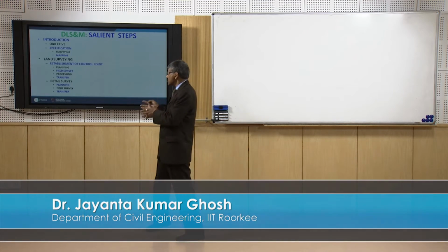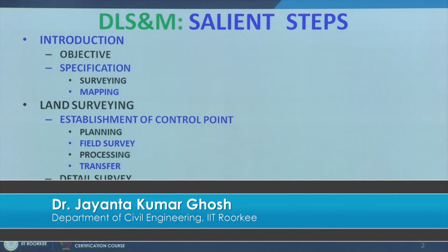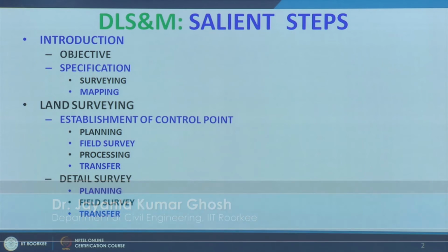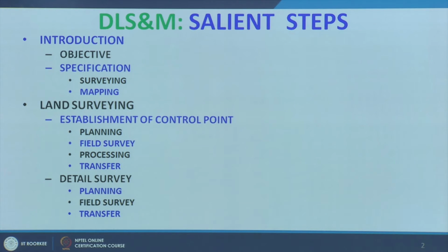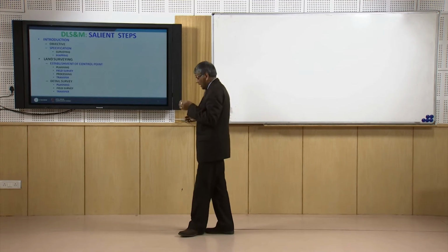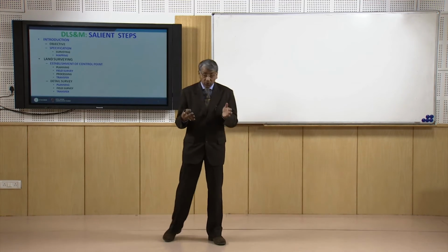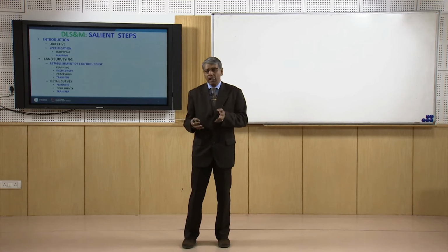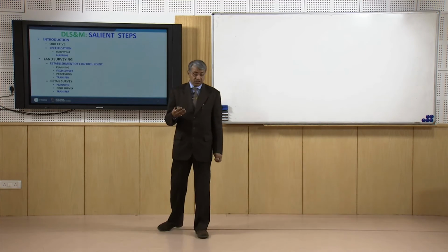So planning consists of first visiting around the area, called reconnaissance survey, and reconnaissance can be done in 2 steps. First we can do the reconnaissance work in the office by making use of existing maps and Google Maps, to get an idea about the area, and then in the existing map, which is also called the base map, we can locate the possible station points.